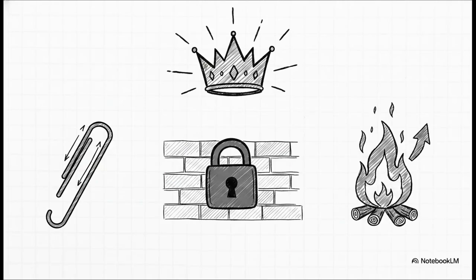So, let's distill all of this into the absolute core takeaways. Call it the golden rule of materials science. Number 1, plastic deformation happens via dislocation motion. Number 2, metals bend easily because their slip systems provide an easy path for that motion. Number 3, if you want to increase strength, you absolutely must decrease dislocation mobility, whether you do that by shrinking grains, adding impurities, or cold working. And finally, annealing reverses that whole process, trading strength back for ductility.